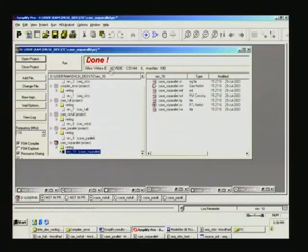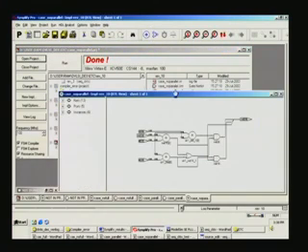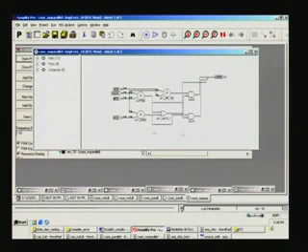So this is the parallel case for which this RTL view is this. You see that for earlier case it was only 3 equal to's there, now it has created additional gates, 3 gates are extra here, right. So earlier it was only parallel case, right.